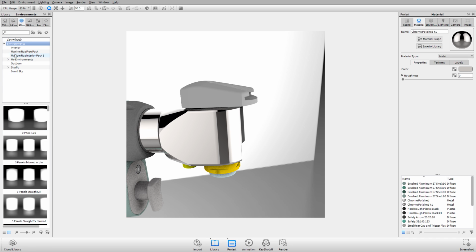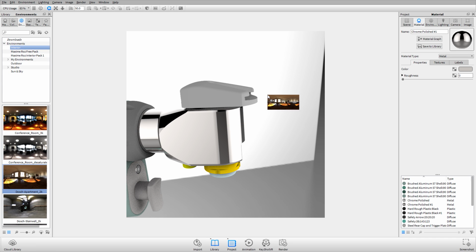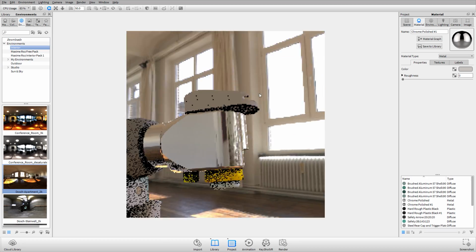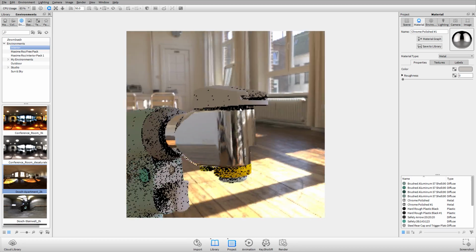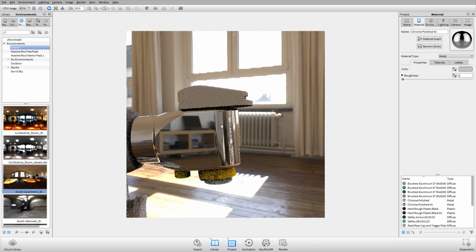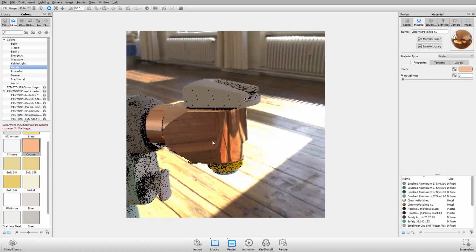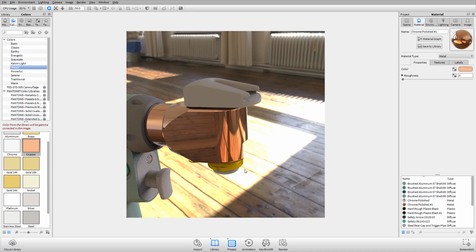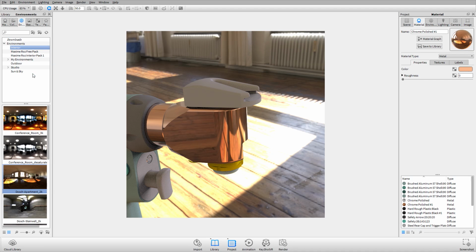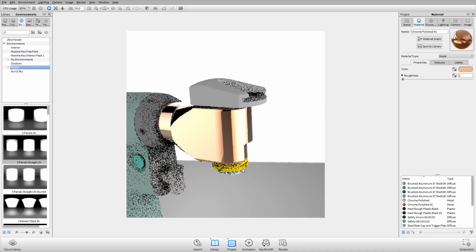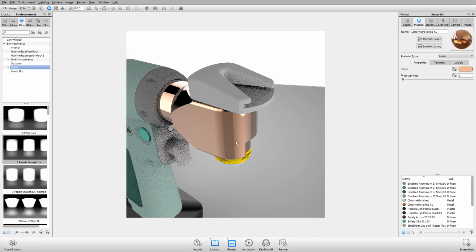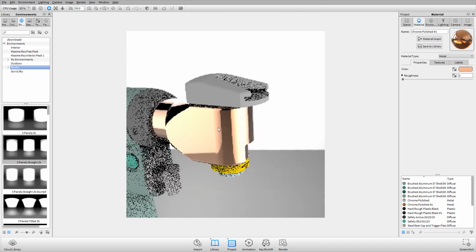If I change this lighting environment really quickly over to a photographic one, you can see that we're seeing the reflections in that material, and we can change that material color to something else, and now that gives us a representation of a different material. So pretty basic stuff, but I just wanted to make sure we talk about it. So what are some of the other properties that we can change with this material? Because what I'd like to do is we'll go through metal, we'll go through metallic paint and anisotropic from a material property standpoint, and then we'll swing back and talk about the textures.